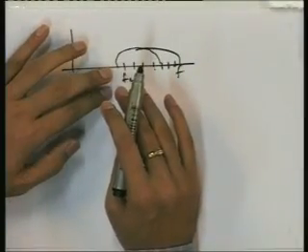Okay. So we will discuss immediately another very similar modulation technique called pulse position modulation. In the case of FSK, we have taken a different frequency for each different symbol. But we can do the same thing in time also. We can take a pulse and transmit it at different times depending on what we want to transmit. So this is called pulse position modulation.